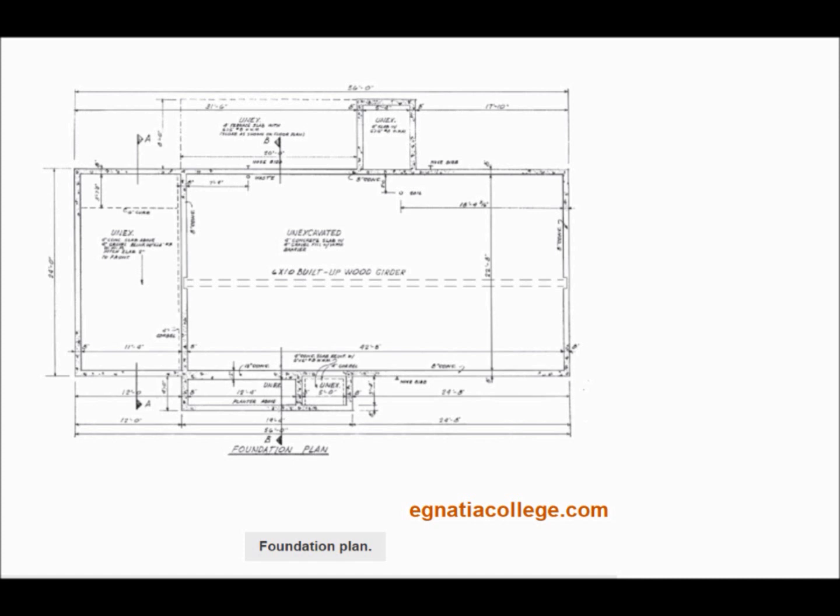In addition to the layout of the foundation walls, dimensions are given for opening windows, doors, and ventilators. Notes on the plan indicate areas that are not to be excavated, concrete slab floors, and other important information about the foundation. Floor plans.